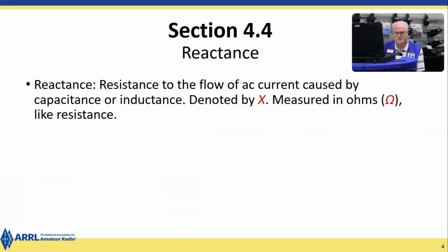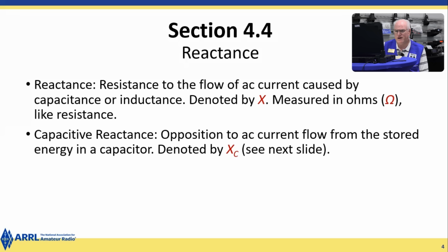Reactance is the resistance to the flow of current caused by capacitance or inductance. It's denoted by the letter X and is measured in ohms, like resistance. Capacitive reactance, which is the opposition to AC current flow from the stored energy in the capacitor, is denoted by XC.